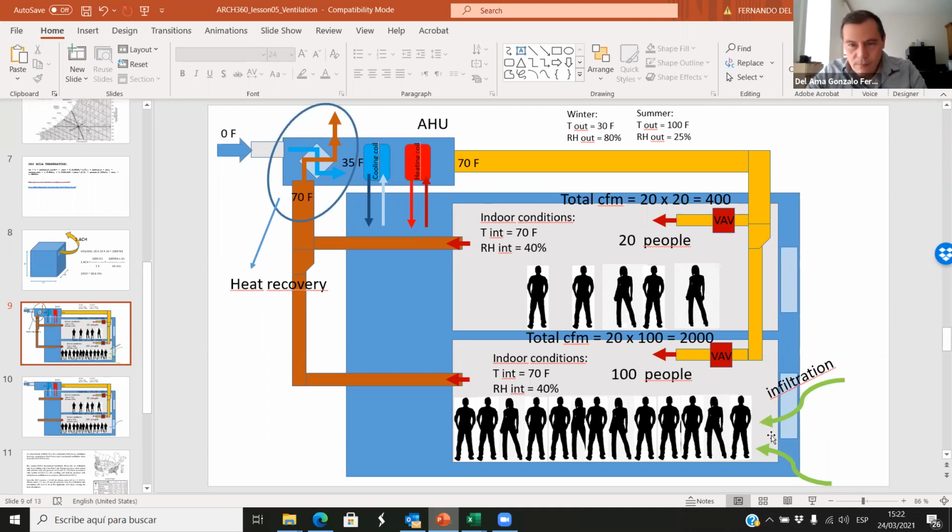It's quite difficult. We need to test the building because in our design there is no way to know. If this is well solved, okay, we won't have infiltration here or here. But what about the real building? We need a test after construction. And this is what Peter Joost is doing as well.